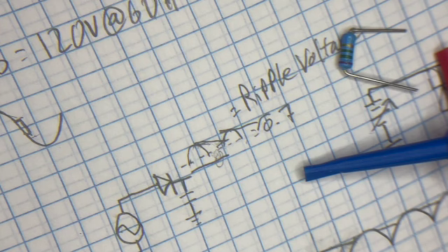Here we go. All right. Absolute maximum value is 30 milliamps. So, forward voltage 2.1, and then we got the wavelength and all that. We don't really worry about that, but we need to look at what we're dealing with.